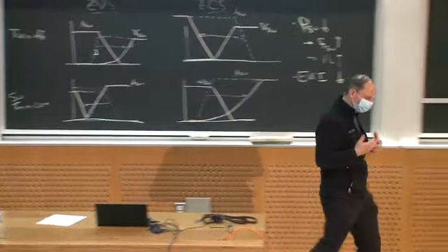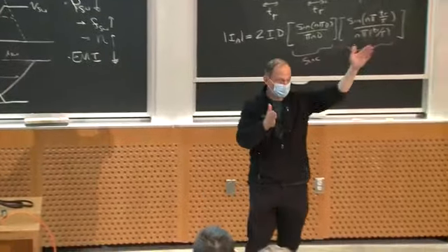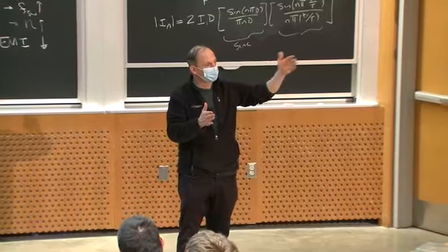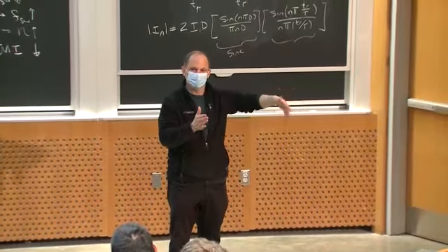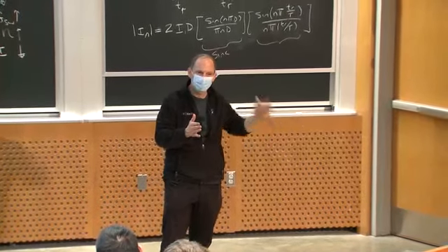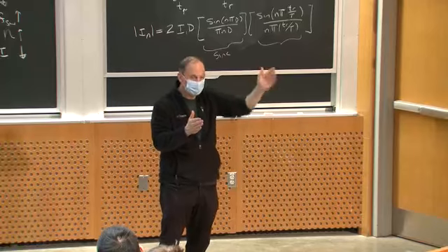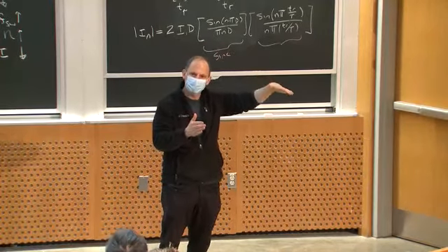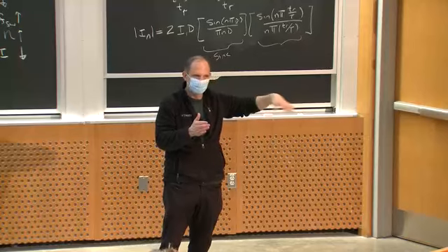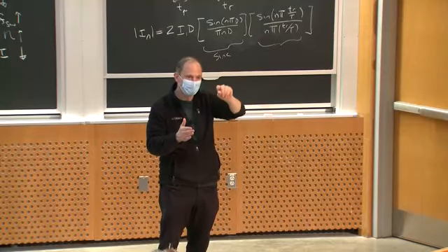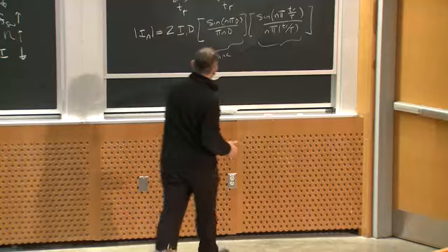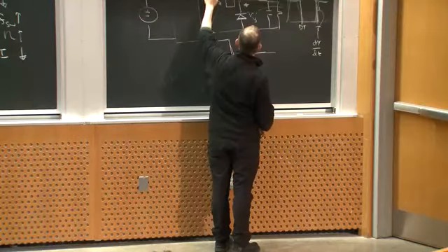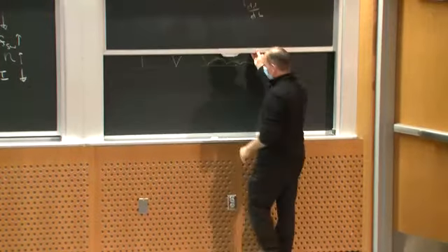What I'm trying to say is, where is the energy content in my square wave? It's sitting at a bunch of harmonics, okay? And I'm not really worried about the individual harmonics. I'm just worried about how the envelope of those harmonic amplitudes falls off. An individual harmonic might be really low, but it will be no bigger than the envelope dictated by the sinc function.